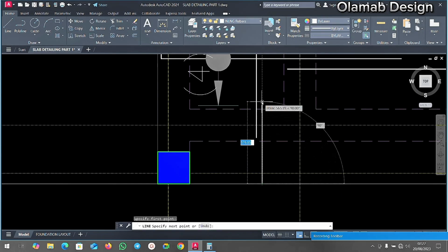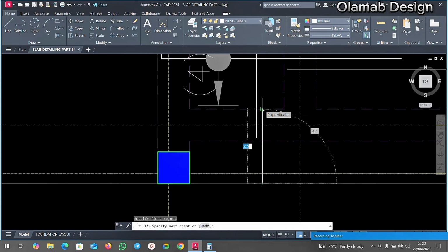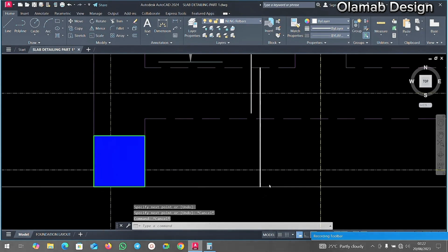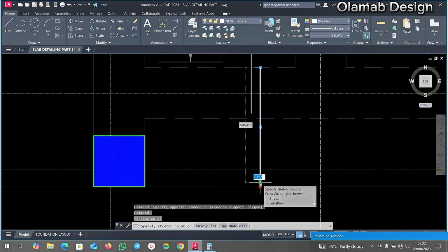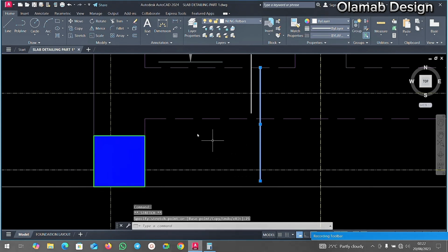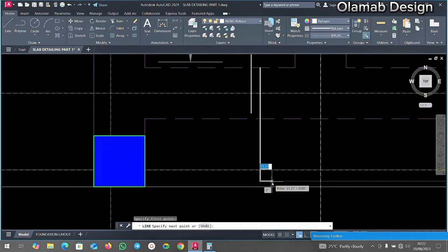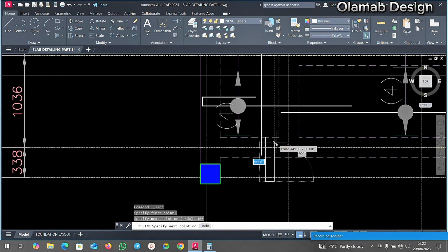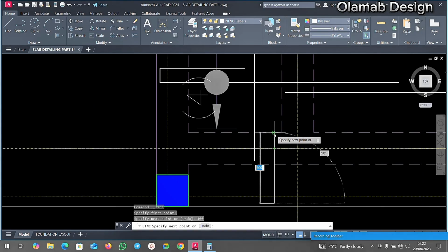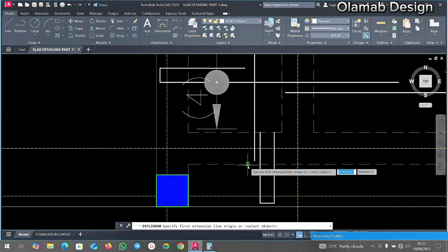Pick it from here to this place. Then select it first. Take it inside by 25. Hit on enter. Take your line. Okay. Take it outside and take 100 mm. And hit on enter for your return. And take this and stop this here first. Okay, so the length of our cantilever I think is just 300.